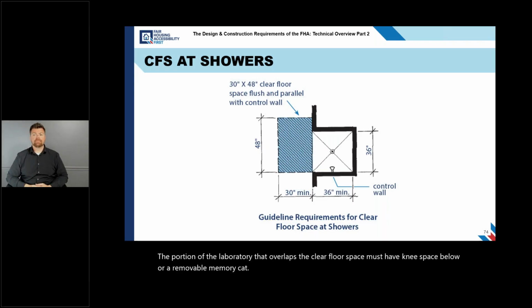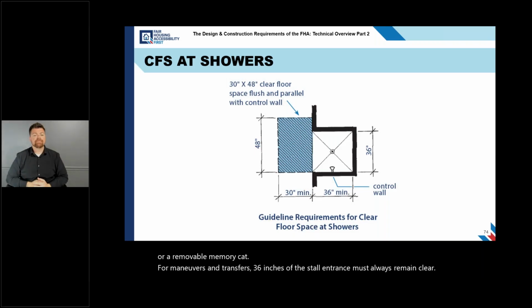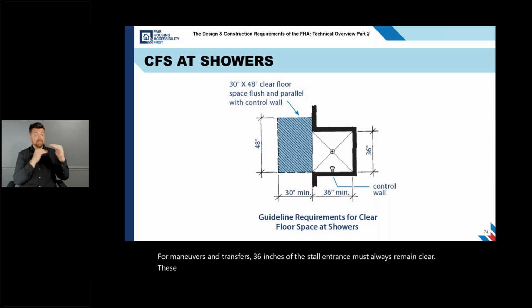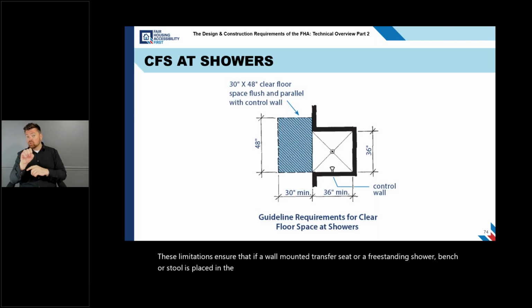For maneuvers and transfers, 36 inches of the stall entrance must always remain clear. These limitations ensure that if a wall-mounted transfer seat or a freestanding shower bench or stool is placed in the shower, there is sufficient space to make a transfer.